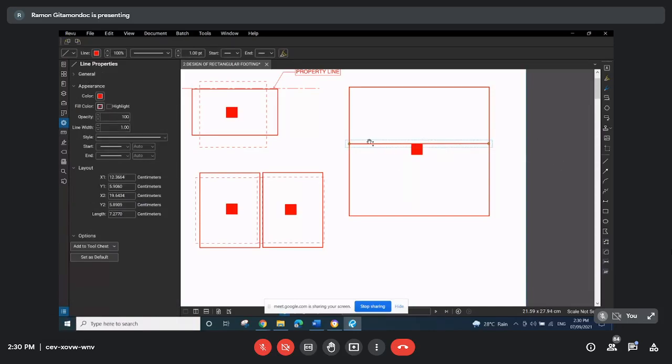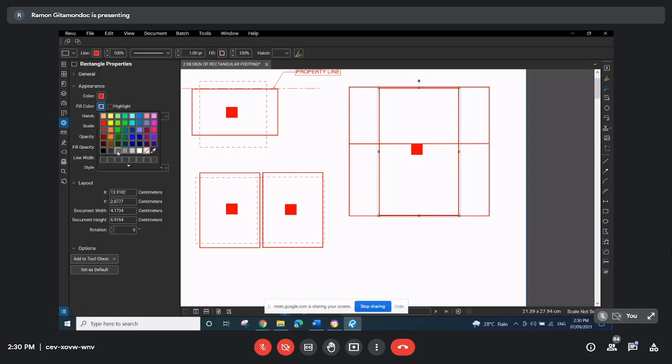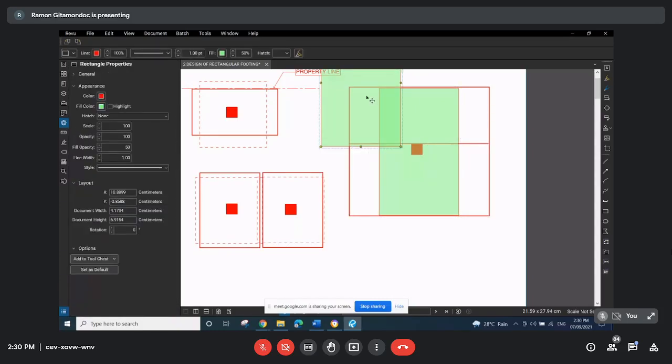So the bending moment is more concentrated in the middle, and less at the edges. So you might consider putting an even distribution of the load. You can consider a certain kind of middle strip in one direction, then also another middle strip in the opposite direction.